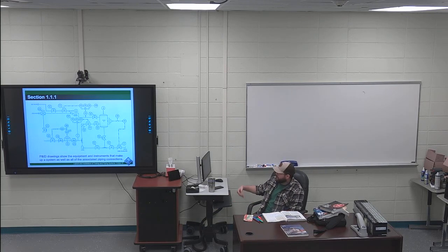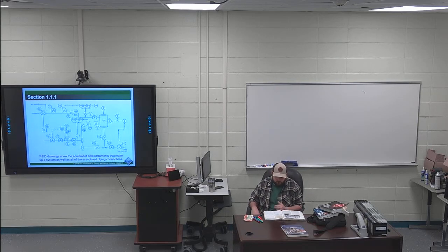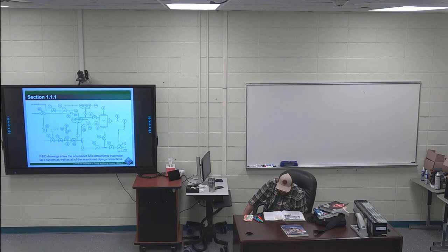So you have drawings, and that's where your P&ID comes in. You have that same P&ID on the bottom of page 3. In the drawing section, pretty much the first paragraph and a half are highlighted, for 2 different highlights. The first paragraph is 1, the diagram, also known as the piping and instrumentation drawing, P&ID. It's usually the initial drawing in the piping design process. This document shows the equipment in the system, the instrumentation requirements, and the piping connections between the major equipment. The P&ID shows the required supporting services that impose design requirements on the system.